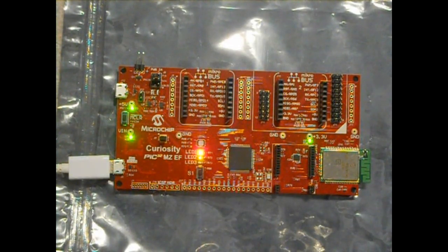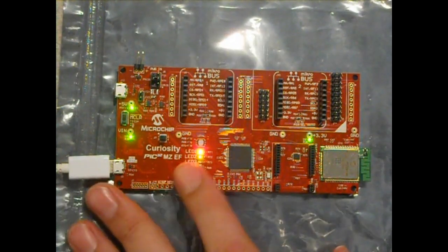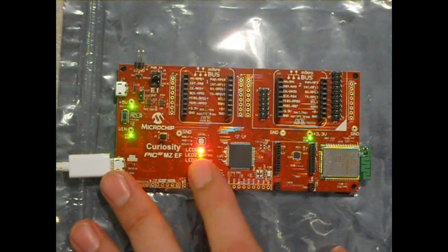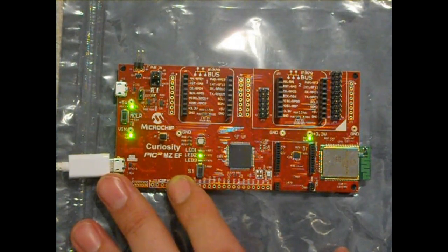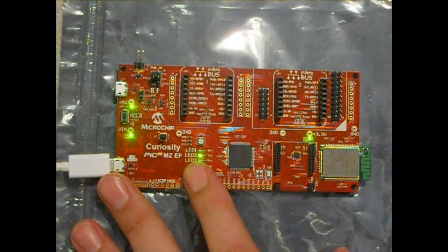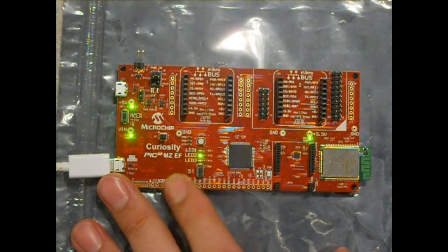Now, the way that you may think to do this would just be to remove the delay, and if you did that, then your switch code would hit more often. The problem with that is that when the switch code hits that often, you have to have more complex logic around how you are capturing the press of the switch. Because humans are so much slower than microchips, pressing this button down, if you had the logic running without the delays, would be held down for thousands or tens of thousands or hundreds of thousands of cycles, and you're going to get some unstable consequences to your LED illuminating.